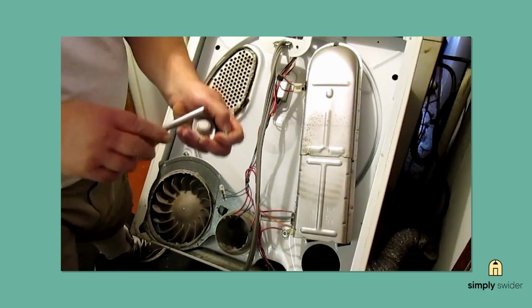Sometimes it's as simple as the door being slightly warped or the hinges getting loose over time. Check for any obvious damage to the latch mechanism and make sure nothing's bent or misaligned.